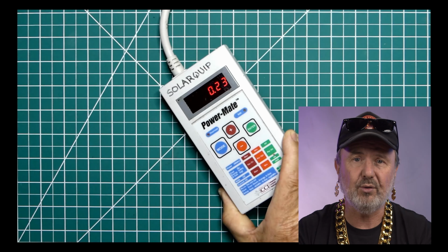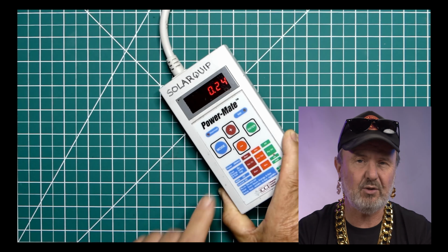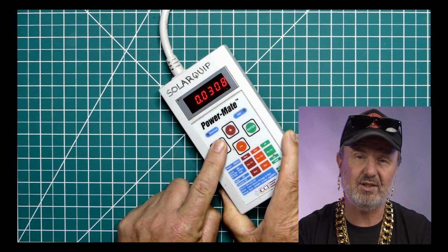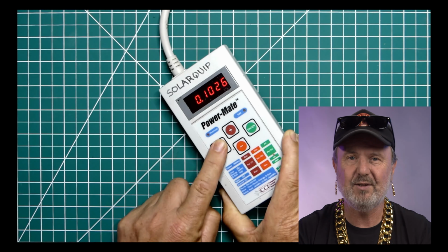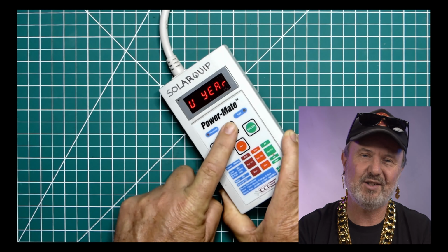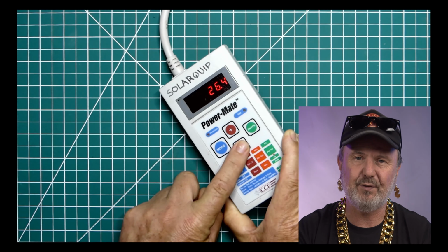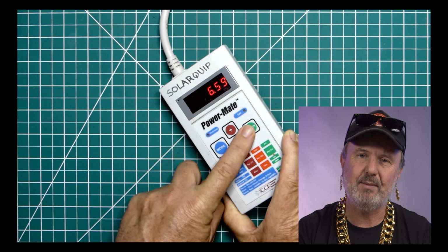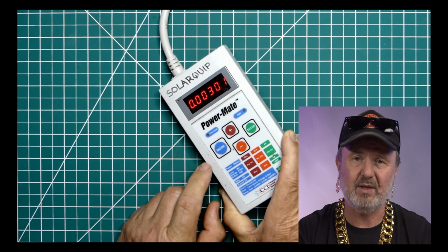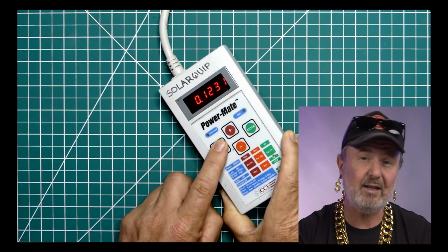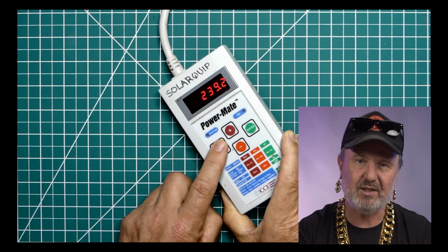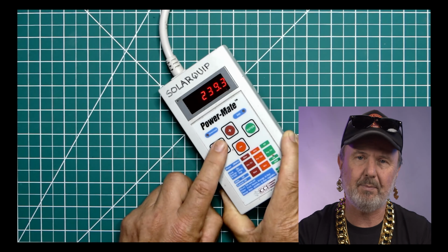It'll log that too, and it'll tell you, I think it's the 100 millisecond surge as something turns on. So it'll show you the peak, it'll show the average, it'll start to do kilowatt hour calculations, which is really great as well, especially for a fridge which cycles. But that peak that it measures is quite useful. So you're kind of measuring the relatively long inrush. So 100 milliseconds is quite long, but it's certainly useful to know what that peak was.